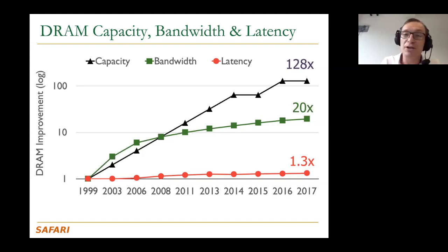And of course, we're going to try to get the best of both worlds. Why is bigger slower? Because you have longer interconnects. Interconnect is really the evil for latency here. That is really what takes time to move the data around, move the voltage, move the electrons around, basically. Okay, so we're going to get back to this.